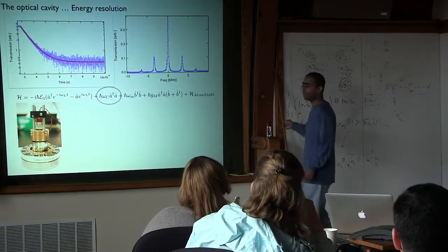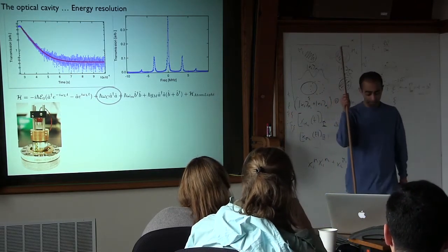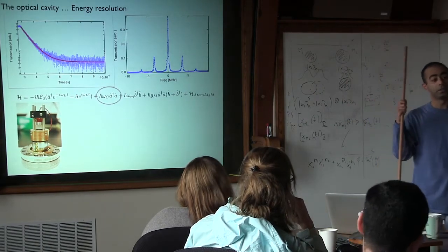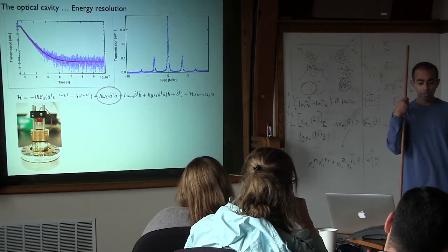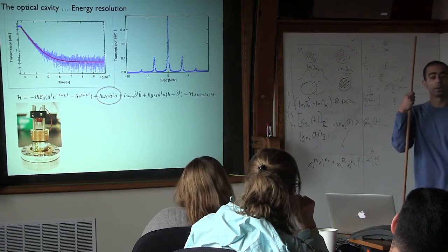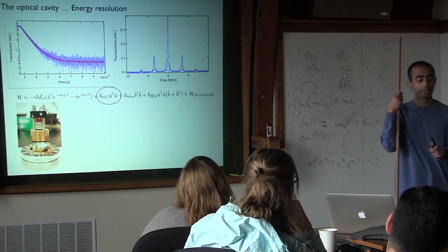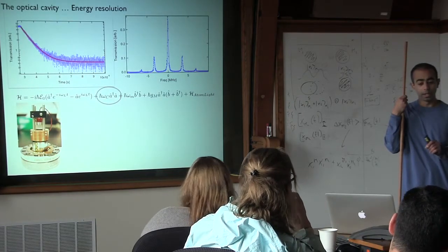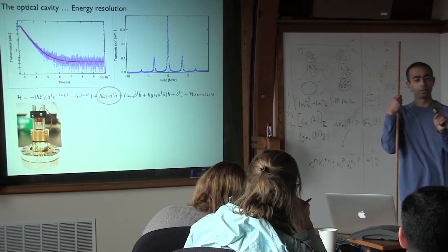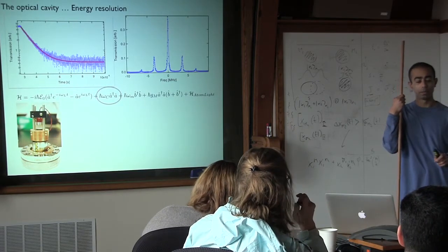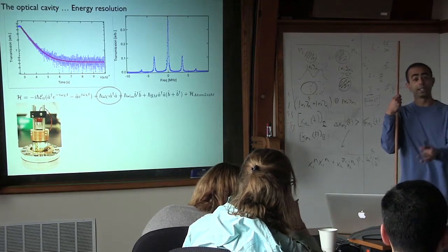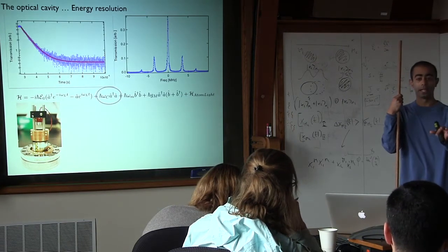Because silicon nitride, the one thing I didn't talk about in my first lecture, is that as amazing as the mechanical properties are of silicon nitride, its optical properties are also extremely good. So we actually had to work very, very hard to measure the absorptivity of silicon nitride, and we could actually only put bounds on it. The imaginary part of the refractive index, at least at the wavelengths we are working in, is less than a few times 10^-7. And it's actually tricky to put a bound on the imaginary part of the refractive index of a solid-state material at that level of precision, but we don't know what it really is. We can only put bounds. It's less than something, and that something is actually extremely tiny already.